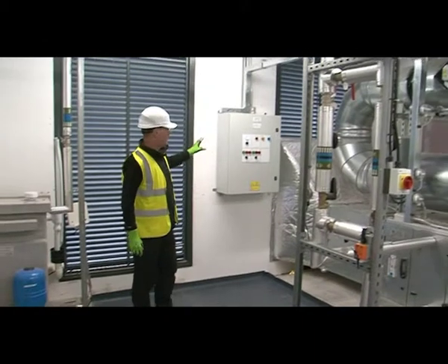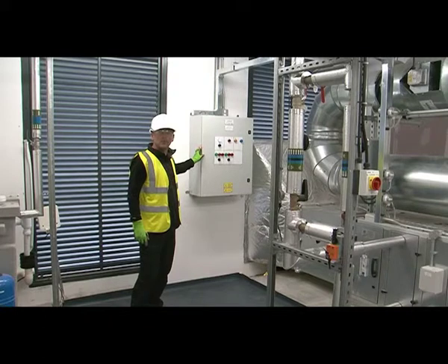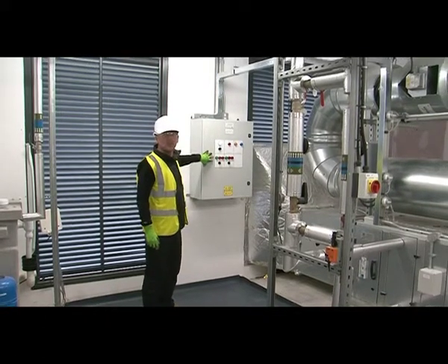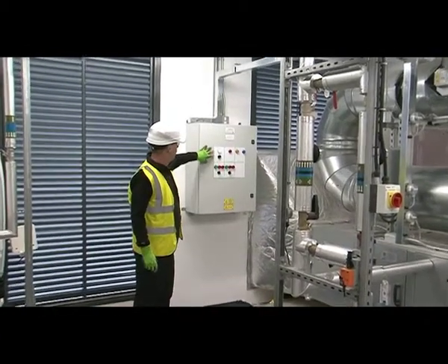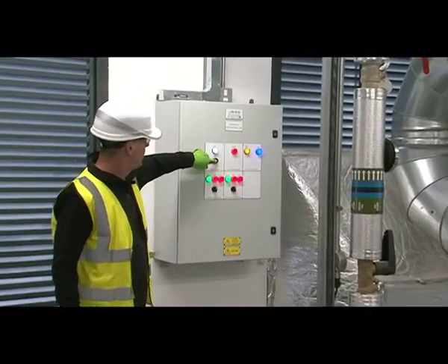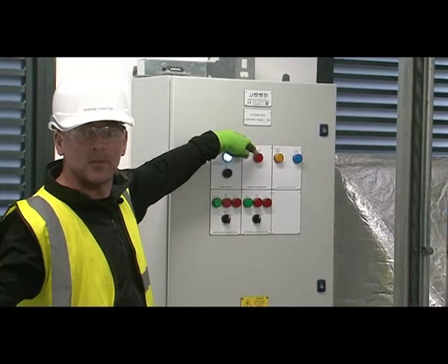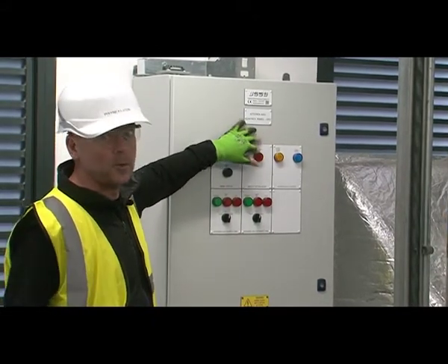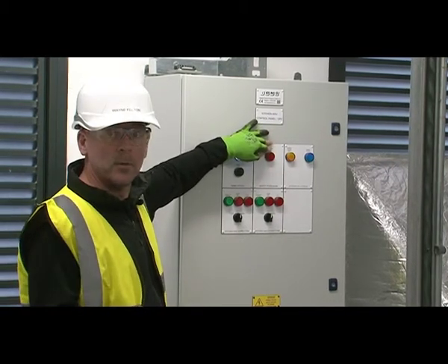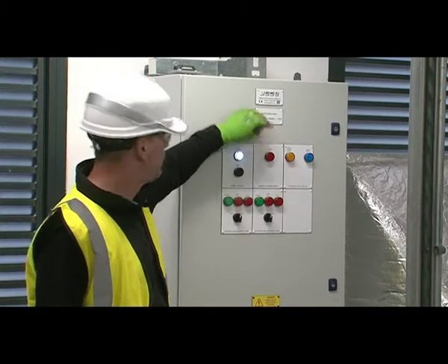Adjacent to this is the air handling unit for the kitchen, and also the small control panel for that. This is linked to the BMS system, but it has dedicated controls for just the air handling unit. On here we have the supply healthy lamp, and again another lamp test button. Adjacent to that we have the fire alarm active status, which again is linked to the main control panel. If that goes off, this will also go off. Just to reiterate, if that goes off, the air equipment will shut down to stop providing air to the fire.